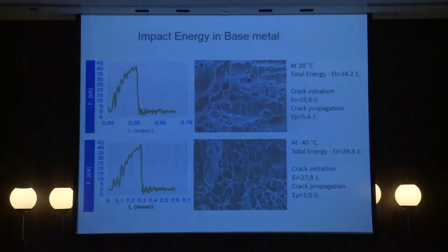The fracture surface is a pronounced brittle fracture. From this we can say that crack initiation energy is almost the same, but crack propagation energy decreases by approximately 4 joules.